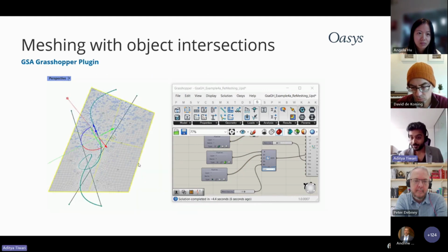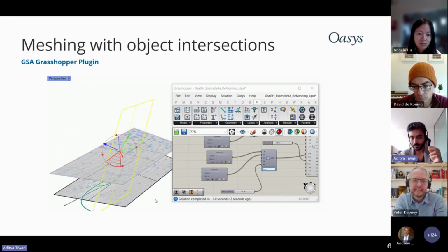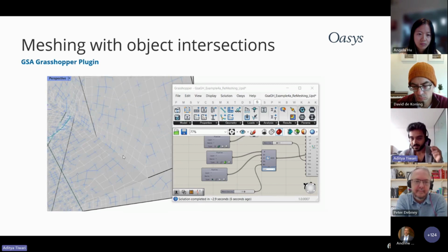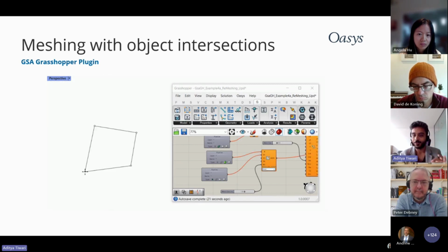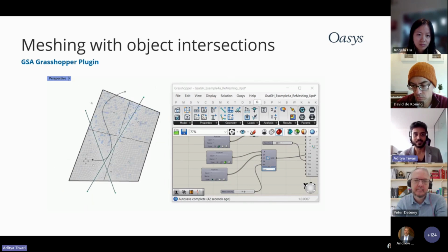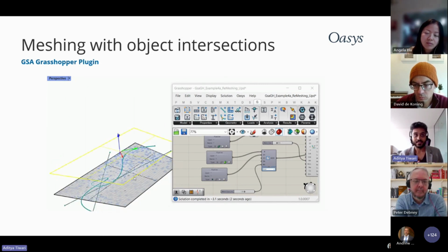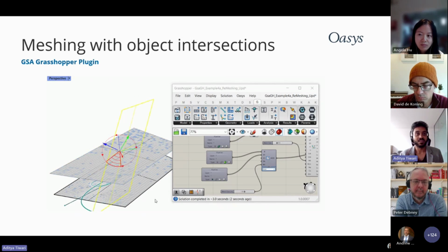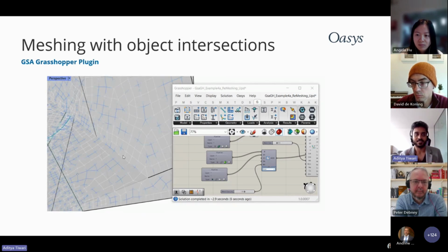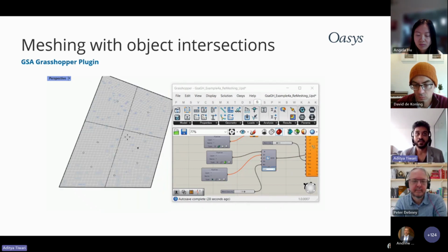So we all love Rhino, and Rhino is great for meshing, but Rhino struggles with FE meshing, which is the same problem: the meshes which Rhino breaks the objects down into should all node out for an FE analysis. And this is what we've solved here. As you see, any intersections between surfaces, lines, points, even NURBS curves are all solved for you in real time at a very high speed. And every intersection is neatly solved, as you see it here. Even all the surface nodes, all the point nodes, etc. Everything is noding out for you to make the geometry modeling easier.